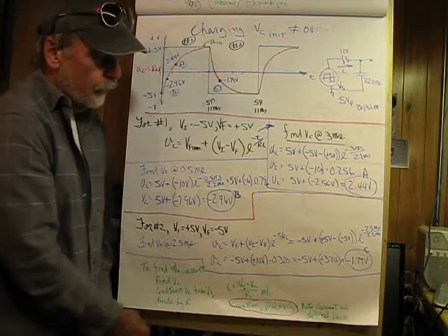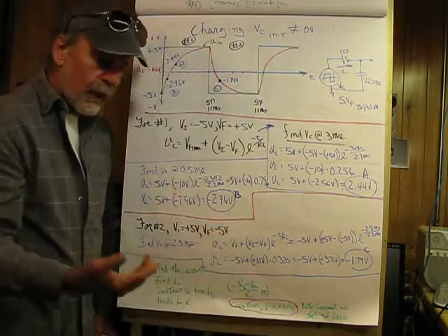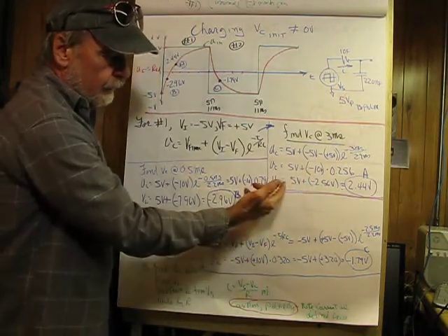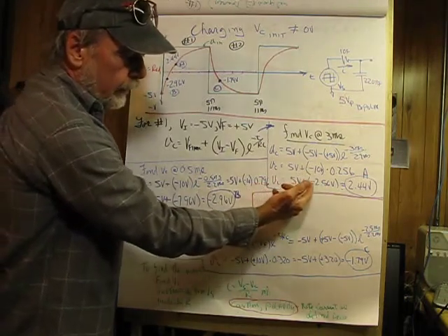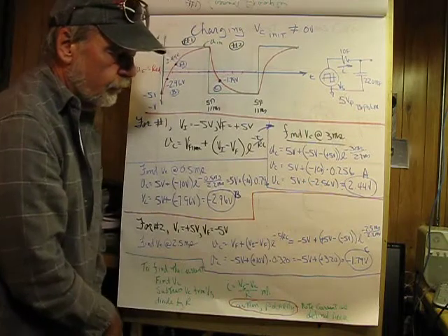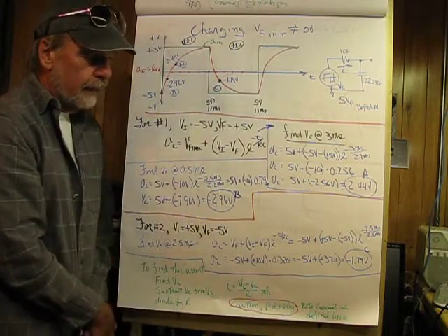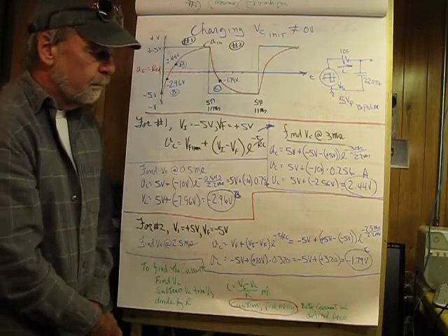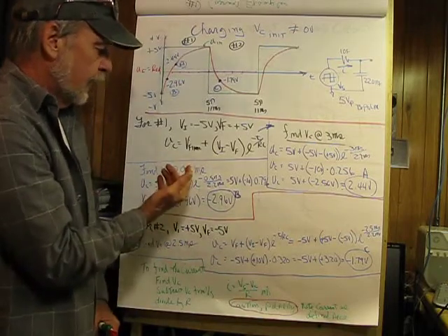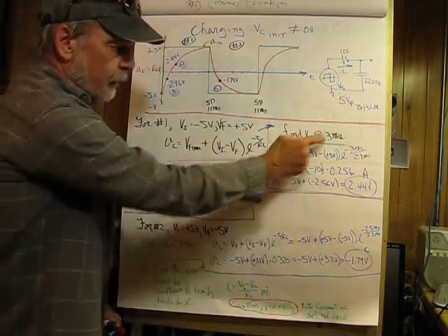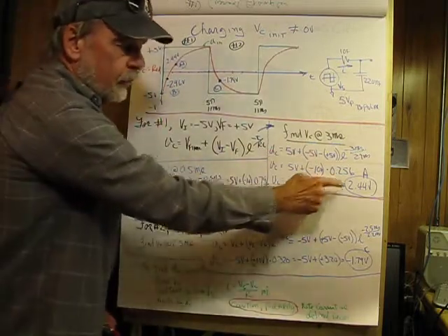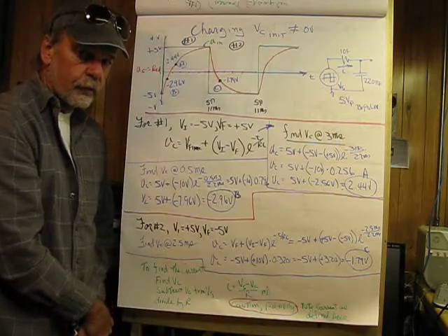Next, by the order of operations, we do the multiply before the addition, and that gives us 5 volts plus a negative 2.56 volts, which gives us an answer of 2.44 volts. So if we want to find our voltage at 3 milliseconds, starting here, it'll be a positive 2.44 volts.